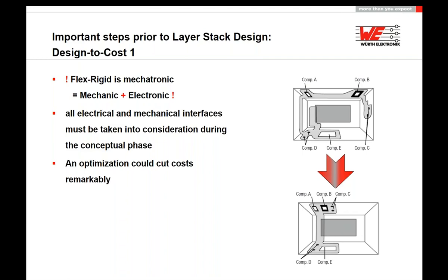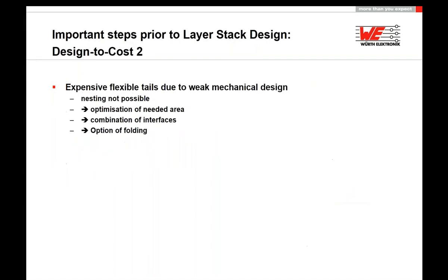But before we start to do the layer stack design, I will give you some hints which are very important. Flex-Rigid is a mechatronic system. That means you also have to consider the mechanical design. So all electrical and mechanical interfaces must be taken into consideration. And if you see a chance to optimize this mechanical construction, you should do that, as this could cut costs remarkably.